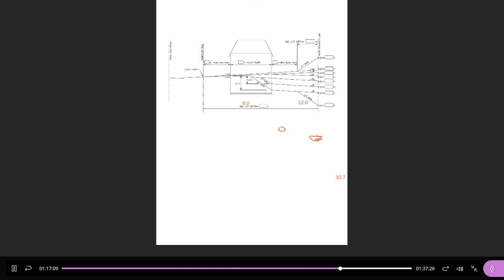And then as soon as you get to the maximum difference, that's the walkout. So the walkout is only one condition. Any difference in elevation between these two lines is going to be a back split. Any difference in elevation between this line and this line is going to be a simple split. But this is the threshold where the deck shows up. I usually ignore this. It really doesn't matter. I don't have to look at it, but it might be worth noting.